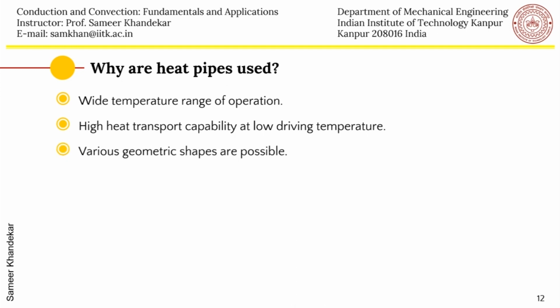and therefore they are very convenient for engineering design applications. The heat source and the sink can be isolated from each other, and you don't lose any thermal potential. The temperature at the evaporator is more or less the temperature at the condenser, and therefore you have it without any voltage drop. In fact, we are able to transport a lot of current or heat in this case. So it is like a superconductor. An electrical superconductor can be made analogous to a thermal superconductor.